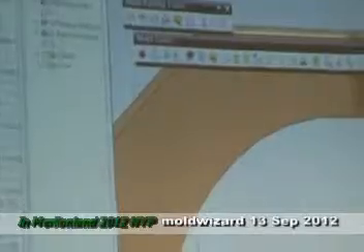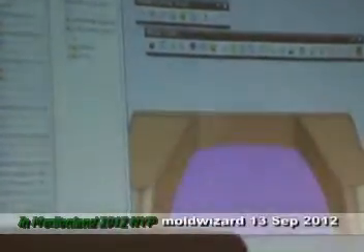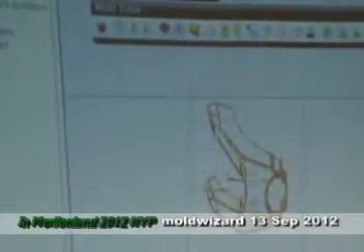Now we can check what the parting line looks like. How about this part? Also the parting line. The internal part should be okay. Or you can change to wireframe and then check. This one should be okay. But looks like a little bit of mismatch. Let's go to the center part.